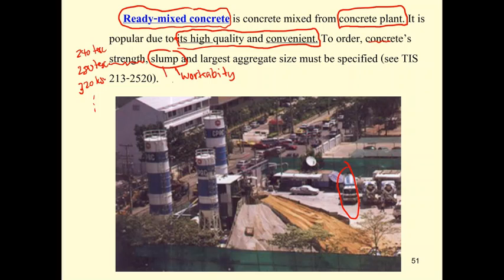However, with a large slump, the concrete will have more water. That means concrete with a large slump sometimes has low strength. Okay, and nowadays we have some additive to increase the workability or the slump of the concrete easily.